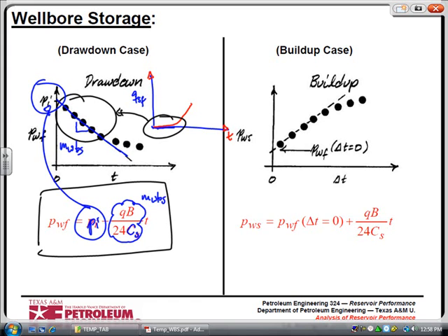Whenever the pressure data tells you that the well is shut in, and the rate data tells you it doesn't know because there's a gap, that's a bad sign. Something that even the most imaginative of you, you're not going to be able to analyze around. You're going to see a lot of continuously measured rate and pressure data. Make sure you do some QC. You looked at the quality control. You looked at the data that I showed you from South Texas. What did you think of that? Garbage. Well, I think you're being polite.